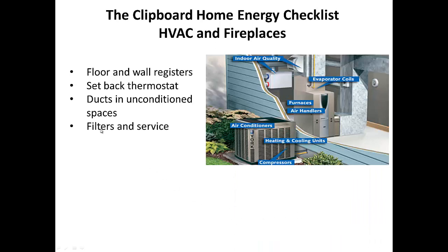Service and filters. Changing your filters on a regular basis is an important thing to do, and ideally you should change your filter at the beginning of the air conditioning season and at the beginning of the heating season. I know that I'm as bad as anybody else in terms of remembering to do that stuff, but it does make a difference. Your system will run easier, and that means you will feel more comfortable and pay less money to the man.